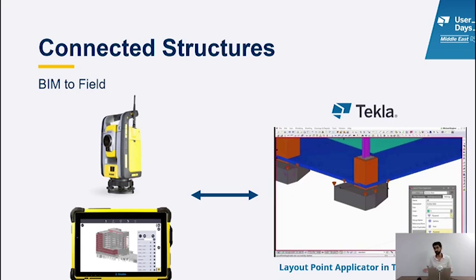And it's needed even in the fabrication, because sometimes you have very complex assemblies, very curved structures with little welds here and there. So doing them manually or using a traditional total station is not really going to help much. But with this technology, the robotic total station will be able to identify the exact position where you have to weld your stiffener or your secondary member, for example.